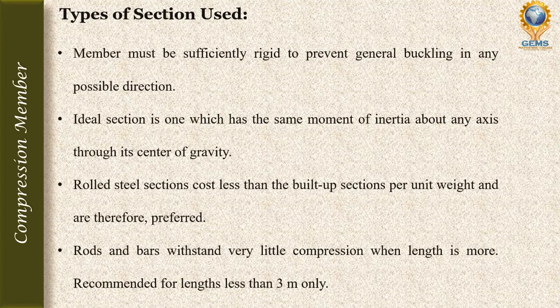The requirements for compression members are more demanding than those for tension members because their load carrying capacity is a function of shape as well as the area and also the material property. Thus, the member must be sufficiently rigid to prevent general buckling in any possible direction.